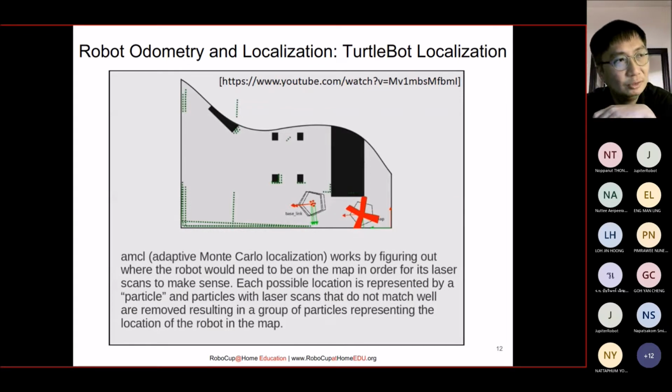That's why later, when you look at the AMCL in Rviz, you can see a lot of tiny arrows, because that is the initial guess of the AMCL of where you're supposed to be. But as you move, your data increases. When I say, okay, my first step, I can see an obstacle in front. Then my second step, in front is not an obstacle, but a space. Then the third step, to the left I saw another obstacle. So if you have this data in a series, then in your map, you can also update.